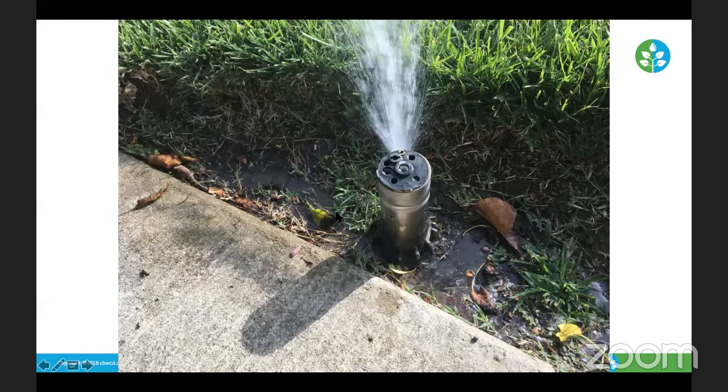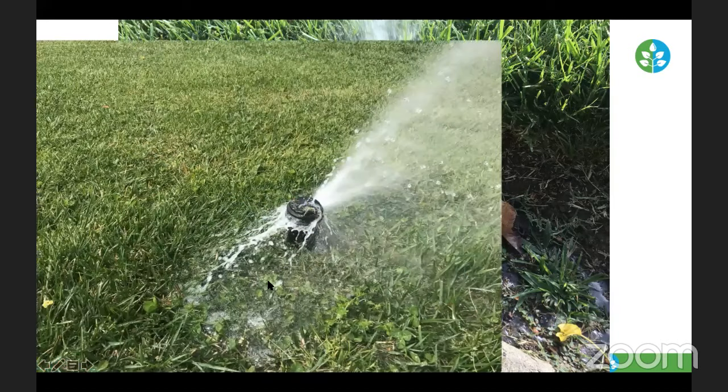So is there a problem here? There's no nozzle in here. This needs to be a more concise stream. The top part of this rotor is beat up and the seal is leaking. So three things going wrong there. Here's a more exaggerated picture that I took where this would flood out immensely because the cap at the top was leaking.